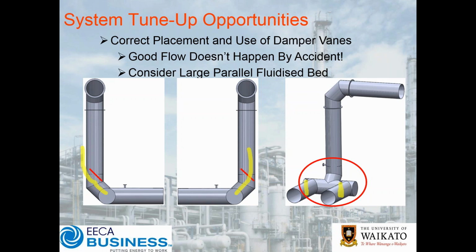Now of course, the first thing we wanted to do was balance the airflow. It was costly to pull those valves out, so we said, look, okay, let's leave them in just to start with. So they were left open at 100%. And if we just rub those lines out for you, what we ended up doing is that valve was then running vertically like so, so it was a lot more neutral.